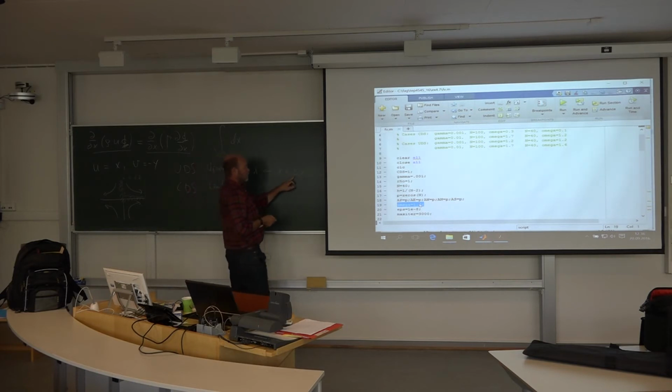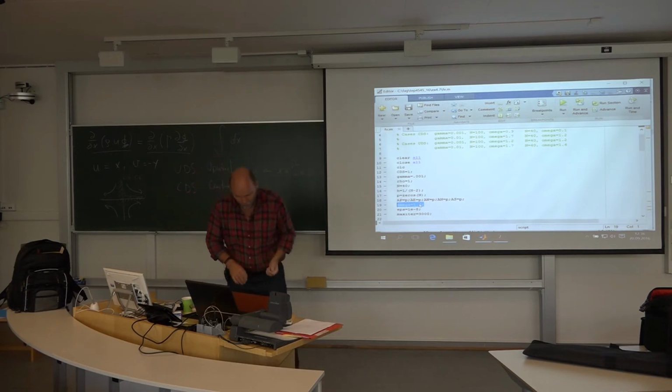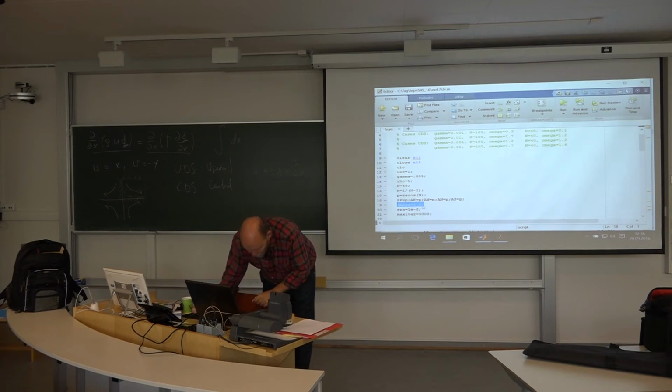And in front of this adjustment you multiply an omega. An over-relaxation overdoes your adjustments; you sort of enhance it. But here, I have to make things stable. So now I have to choose it very small. I think all the way down to 0.1 or something. Let's try 0.3.